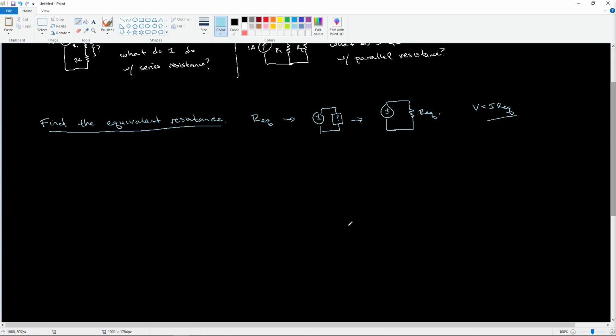So in order to find the equivalent resistance, we're going to want to step back and talk about resistance by itself. So resistance R, we were talking about in the Ohm's law video part 1, is this rho parameter times L over A, where rho is the resistivity of the material we're dealing with.